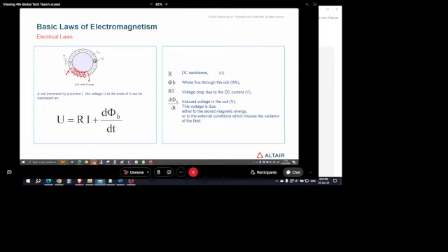Okay, so this is what we are going to use later on to build a matrix of voltages and then move to the Park model. Once again, R is the resistance of the coil. Phi B is the magnetic flux seen by the coil. And then it's logical to say that dphi by dt is the voltage induced on the coil due to the magnetic flux variation.